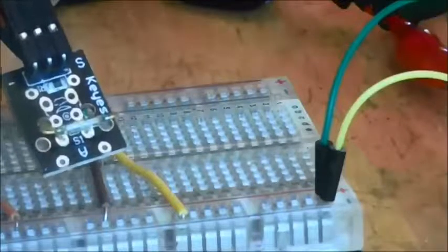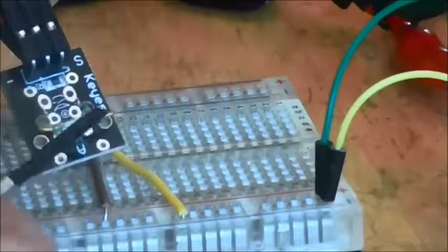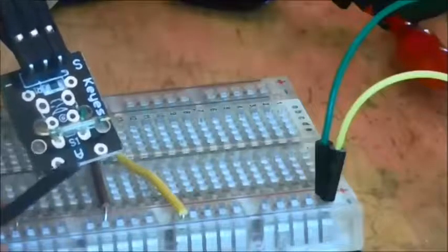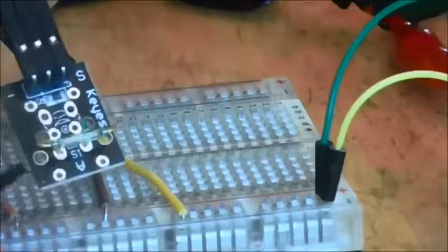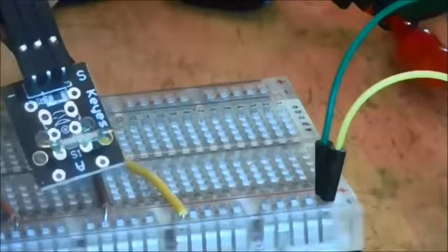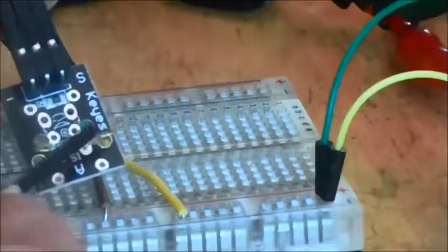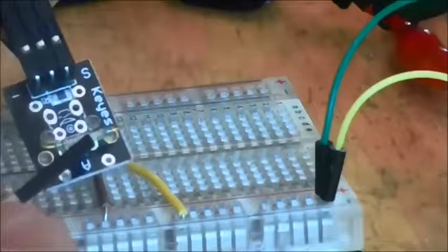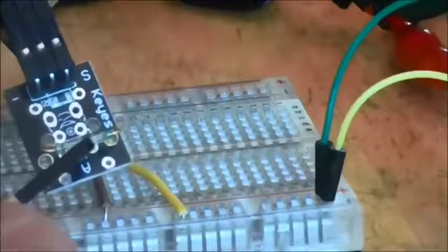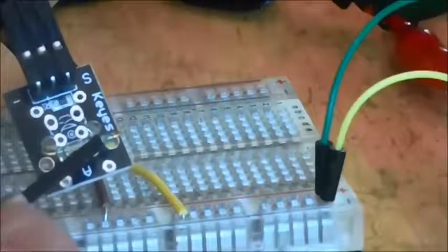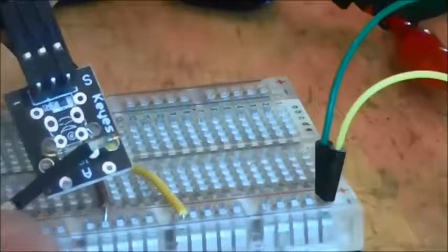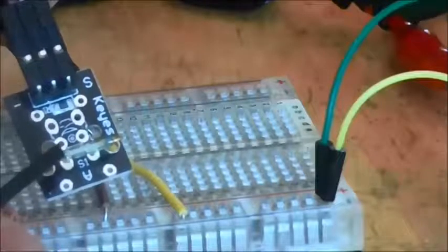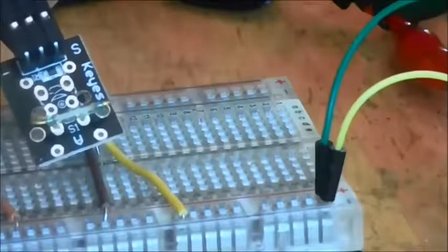The next thing we need to look at is a reed switch, and this is it here. It's mounted on a breakout board to make it easier to clamp down onto plastics or woods or whatever you're going to mount it to. But the reed switch is actually a form of contact switch, and it's 2 strips. Normally they come together like that, but when you put them in the presence of a magnet, they'll come apart.